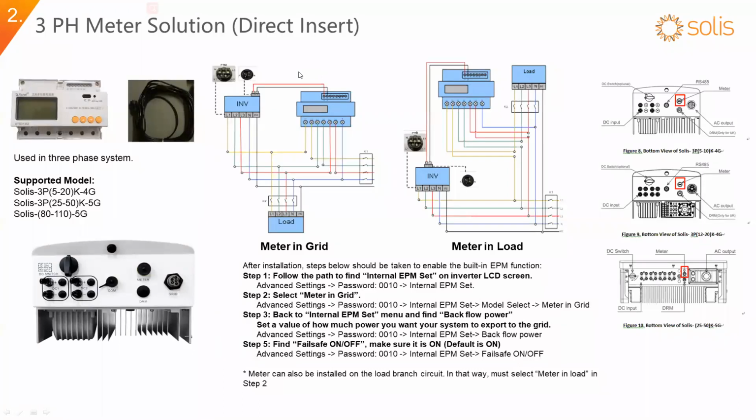All the necessary connectors will be provided in the package, so you don't need to worry about the connectors. The pin diagrams of the connector should be in the user manual of either the EPM or the inverter. And they should be connected to the EPM for data logging purposes.